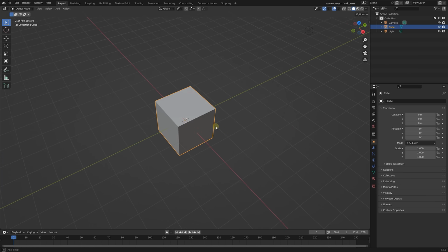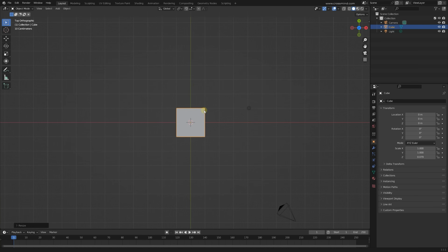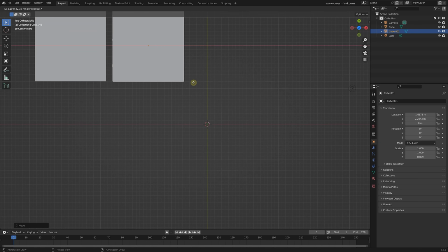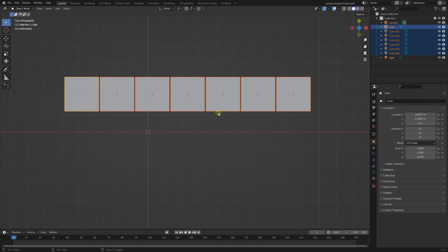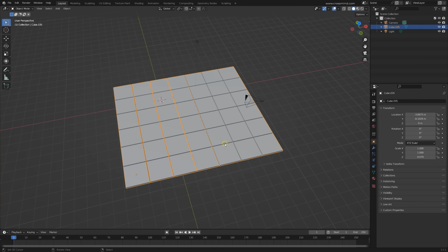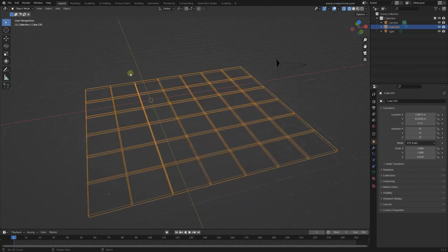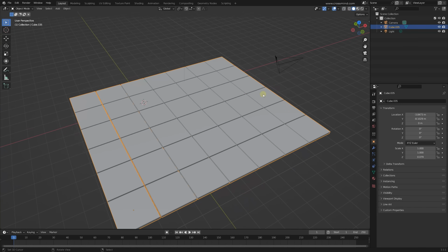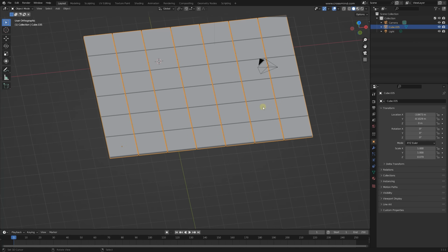Before we start the animation, I just wanted to clear something up. Let's say you're bringing geometry from outside of Blender, you have something like tiles, and Control D. When you import geometry from external software, sometimes you have everything combined into one geometry, and the pivot points, the origin points, are not really aligned well. So there are a few things you need to take care of before you start animating.